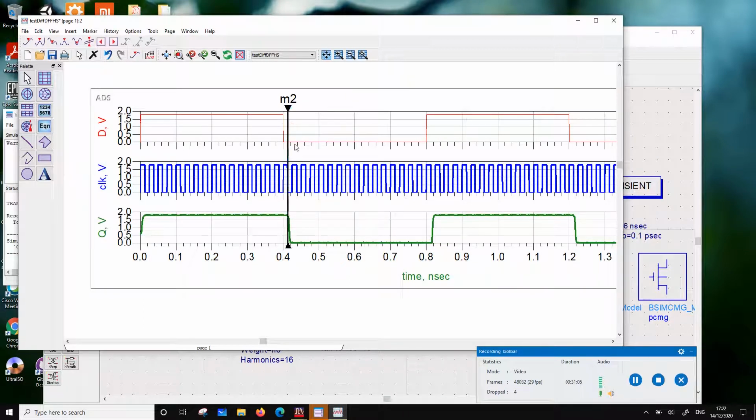and this is not as bad as the previous one, because half of this I have gone through the transition already, right? And when the rising edge comes, I have already transitioned, so I have a hold time there, or setup time, sorry. I have a setup time over here, a lot of setup time I have over here.